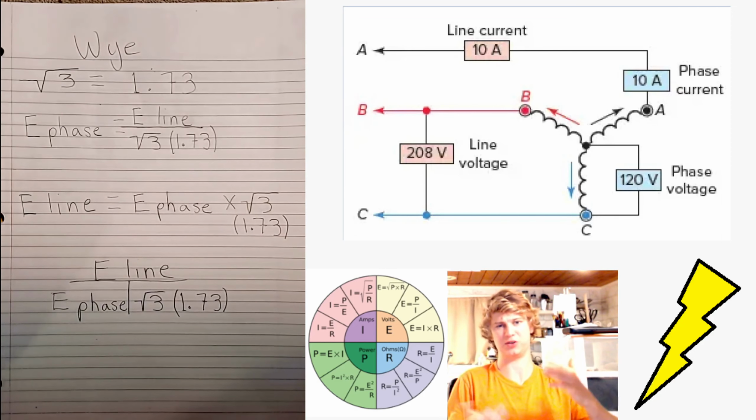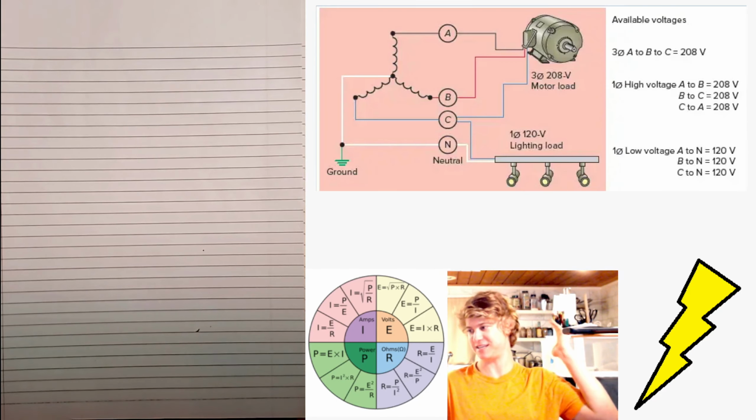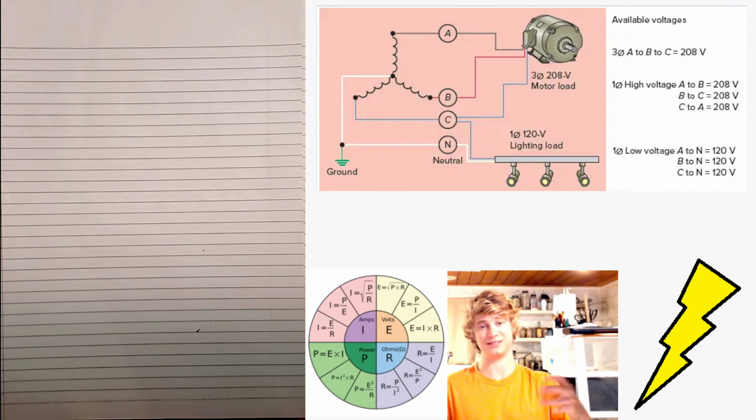The three-phase 4-wire Y system is very common and is the standard system supplied by many power utilities to commercial and industrial customers. Okay, so now as we can see in the picture above, we see a 4-wire Y-connected alternator capable of supplying power to a building. It can deliver both single-phase and three-phase power, and both 208 volts and 120 volts without the use of a transformer. Just depends on how it's wired.